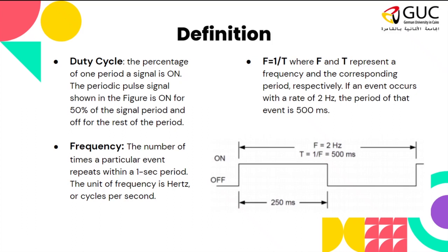Pulse width modulation is an approach to have an analog output in digital means, meaning that we alternate the voltage output by turning the signal on and off with a particular percentage over one period of time, to have the average voltage which we want.